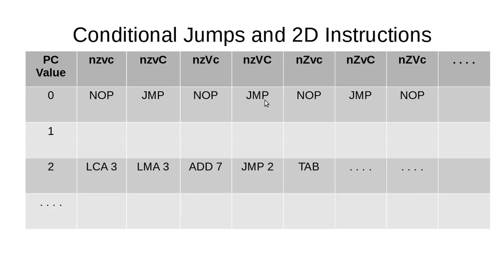So let's take as an example that the last ALU operation calculated a 0 and stored it somewhere, and the flags value is 0 and everything else is turned off. Okay, so if we now jump down to do jump if carry is set, we will look up only this instruction for program counter value 0. And we'll see that currently it's doing no operation. So we'll simply increment the PC value down to 1, and of course that won't affect the flags value, so that means we'll also move straight down, and this will be the next instruction that gets performed.